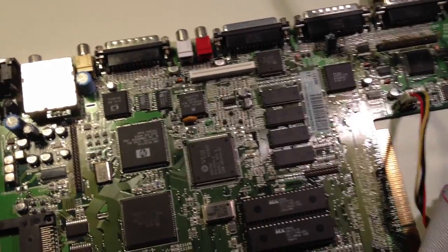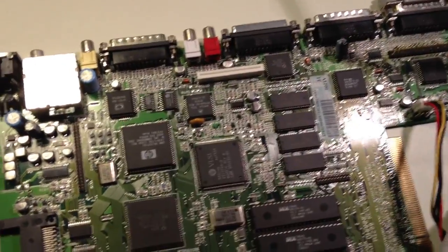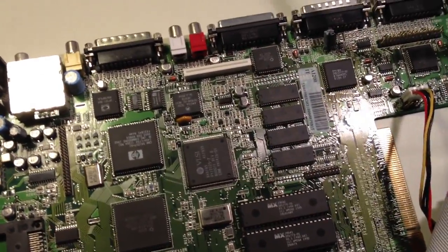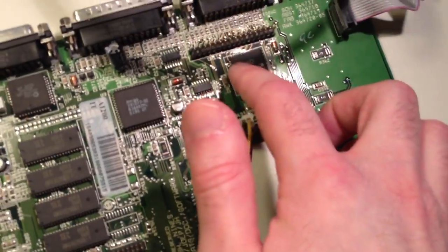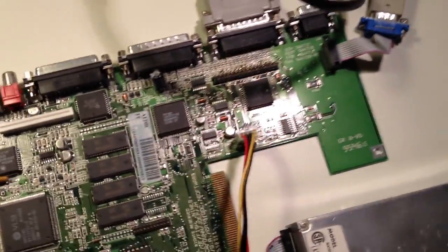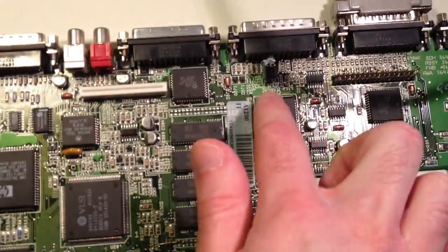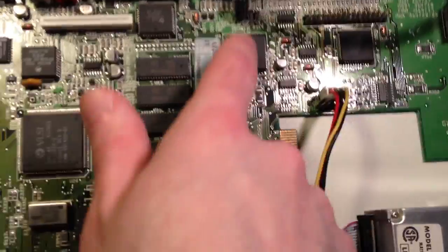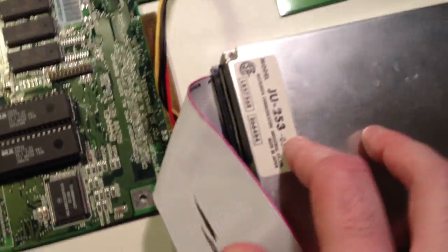Okay, so to start with, I would just like to mention that when talking about an Amiga, the so-called floppy controller is actually quite an abstract term in a sense, because the floppy functions are not controlled only by one chip, but they are actually controlled by several of the custom chips on the motherboard. For example, here we have the even CIA, and that is responsible for stepping the heads, among other things, and Paula is the one that is receiving the incoming data, and it's also putting out data to the floppy disk drive as a write operation is being performed, and Gayle is responsible for the motor on signal to DF0, if I'm not mistaken.